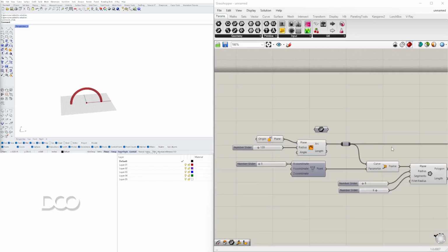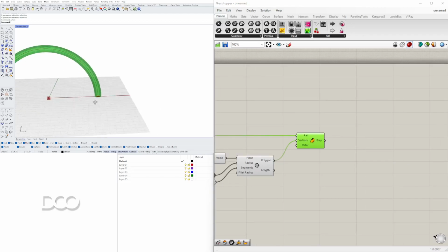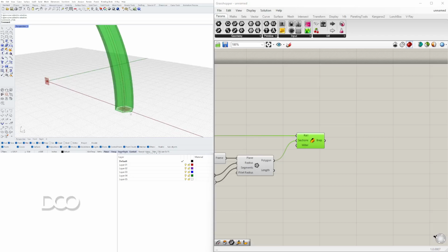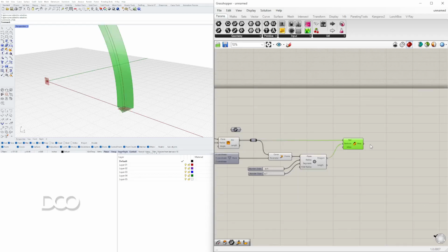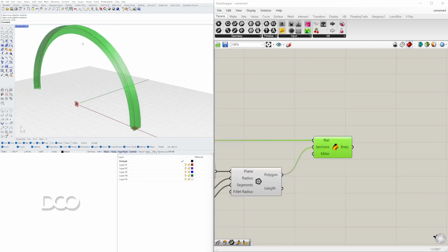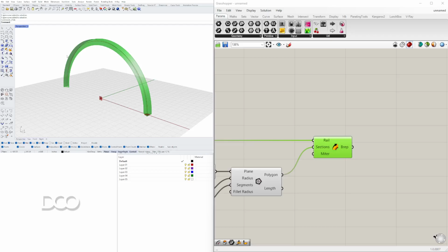The next thing we'll do is go here to our output, and let's take a look at our B-Wrap. So it says open B-Wrap. We know that this B-Wrap consists of that hexagon, so there's 6 segments. Let's bring this down to 3 segments. And let's take this B-Wrap and we need to subdivide it. There are different ways to do that. I'm going to show you one of the approaches that will maintain the arc, or the flow of that curve. We'll go with one approach, and if there's a different approach that I feel is better, I might switch to that one.